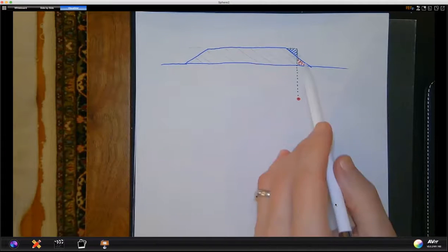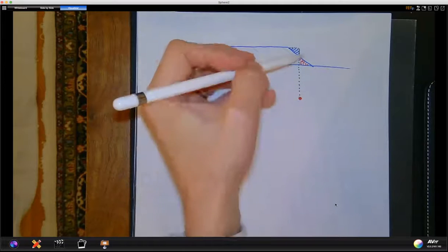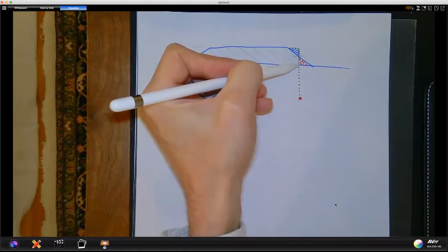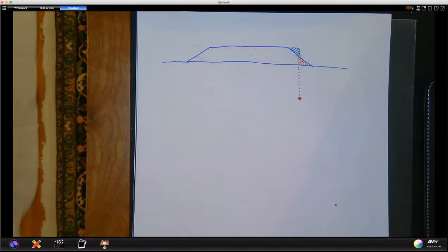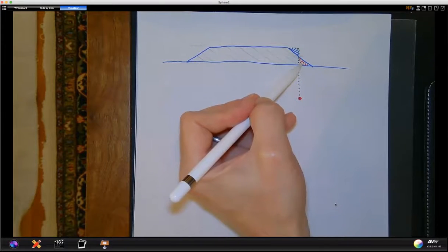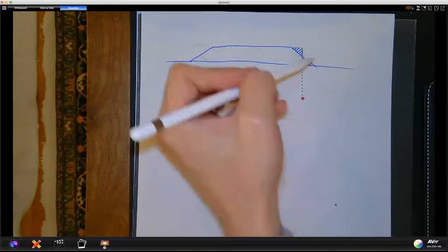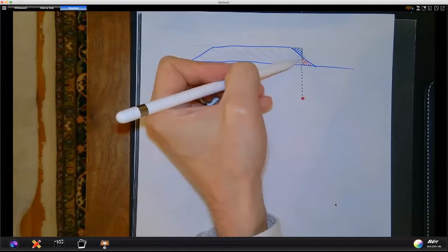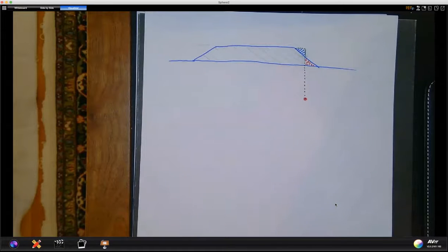So for that red polka dot, the Q naught would be associated with this little stress amount here. The full height of the embankment being modeled, and in this case, it's just that little triangle being modeled for that one entry into the chart. And that would be your value. So Q naught would be associated with this little h times the gamma of that embankment soil.